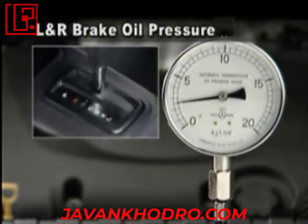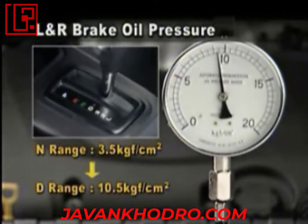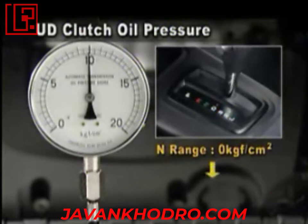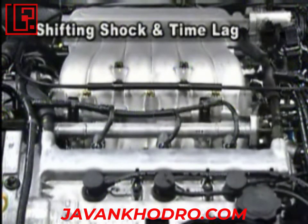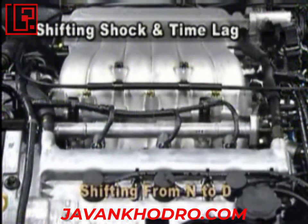The oil pressure of low and reverse brake increases to 10.5 kgf/cm² from 3.5 kgf/cm² when D range is selected from N range. On the other hand, oil pressure of underdrive clutch increases from 0 to 10.5 kgf/cm². Therefore, check the related flow path and parts of underdrive clutch of oil pressure equipment first, if shifting shock or time lag occurs when shifting from N to D.